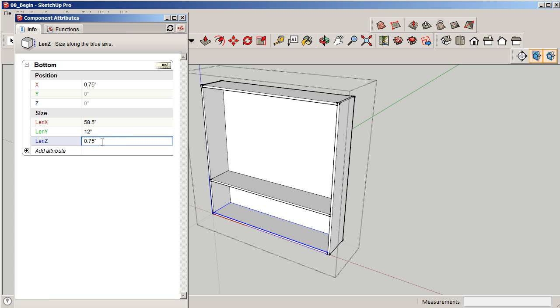Now, last but not least, this will actually be my material thickness, because we're going in the Z direction. That means basically the thickness going up along this blue axis. And I want that to equal the bookshelf's material thickness. There really shouldn't be any movement because we already pretty much had everything in place. Hit tab, no warning signs, so we are in good shape. We've applied pretty much all the formulas we need for our bottom piece, and we can now control it.